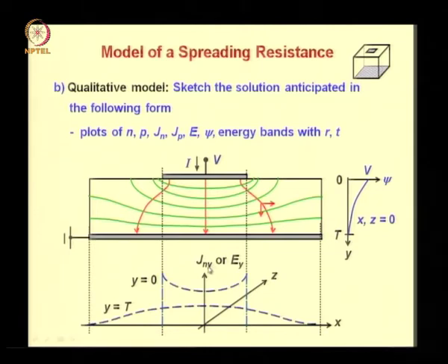The y component of the electron current density Jn or the electric field had this appearance over the top and bottom contact as a function of distance. The edges had higher values near the top contact because the field at the sharp corners or edges is higher than in the center.